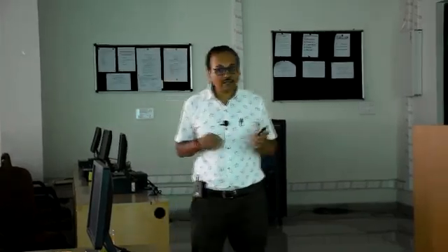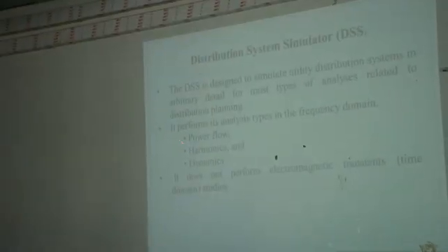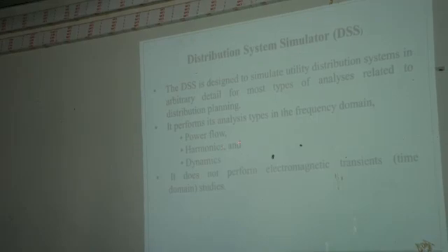So what we can do, and another beauty of this OpenDSS is that all the codes for different IEEE standard bus systems are there, like IEEE 13 bus, IEEE 30 bus. Okay, even a large network is also available there. That is the IEEE 8500 node. You can do power flow study here, harmonic analysis is possible, dynamic study is also possible.